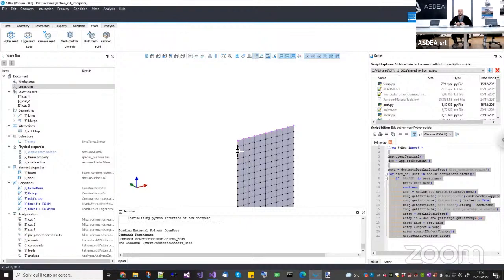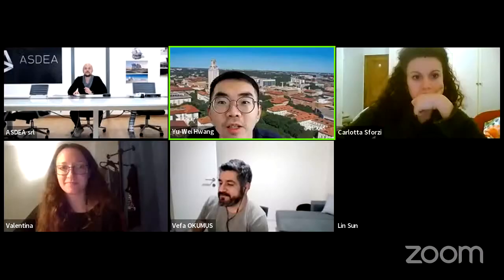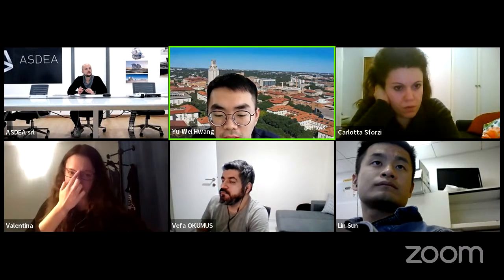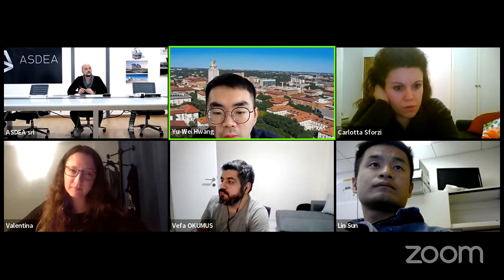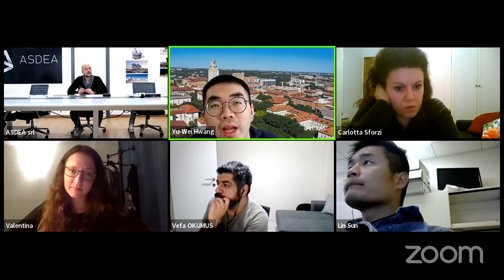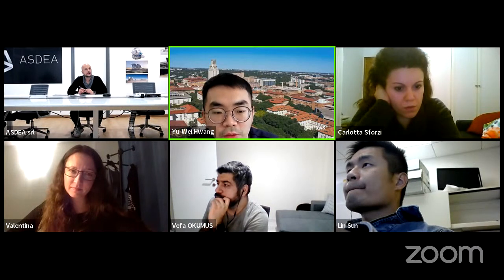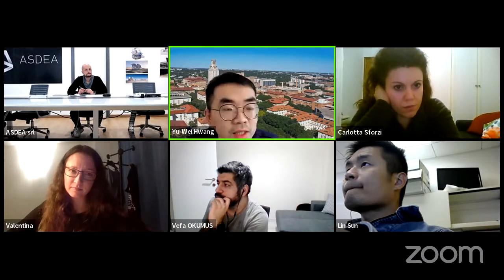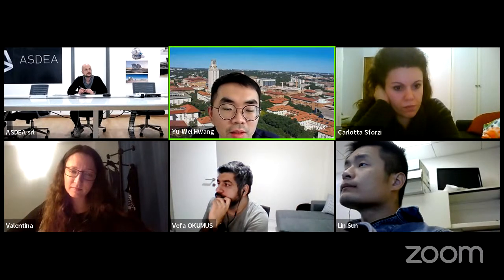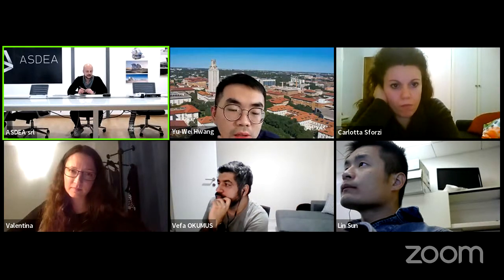Okay? Hey, Massimo, thank you for, can you hear me? Yeah, I can hear you. Okay. Yeah, thank you for all your help on this. And it's just like there is some, I'm not sure it's a bug or something else, but if we are using some soil material like PDMY or PIMY, and when we use SSP brick UP or SSP quadrant UP element, it looks like it can show the stress contour, but if I try to plot the Gauss point, then it doesn't show anything in the post-processing. No, actually, it is a known problem.